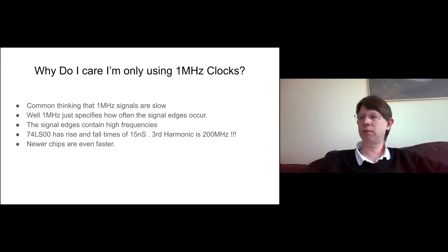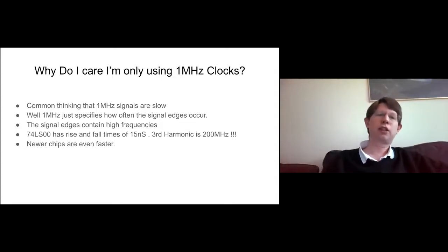And if you're designing using newer chips, FPGAs, CPLDs, some of these chips have 1 nanosecond rise and fall times quite easily. And that can present problems. Even though you might think you're just using a 1 megahertz clock, it's the edges that are important, the edges that give you the energy.